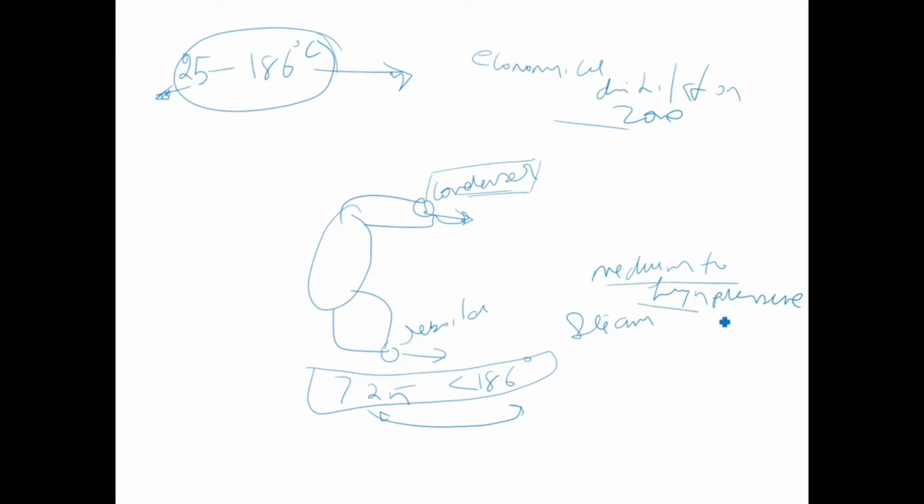You will not have a clue if you look at these things, but since I'm saying that and you are listening to my videos, you will know what I'm writing here. This is medium to high pressure steam. That's more than enough to create such temperature. So 186 degrees centigrade: if you use high pressure steam, that's enough to create 186 degrees centigrade of heat to boil your fluid mixture, in order to create what we want, some vapor phase which we need to collect in the top.